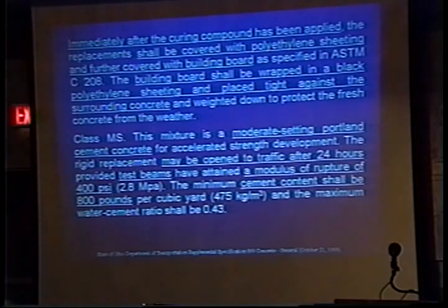And keep in mind, we're talking about pavements here. We're not talking about your patio or your driveway. So if you leave a little footprint in it, or if you mar it a little bit when you cover it up, who cares? Okay, get it covered. That's the key. Obviously, you don't want whatever you're covering it with to sink down into the concrete, but get it covered immediately.